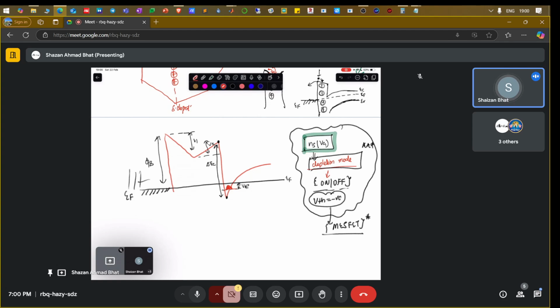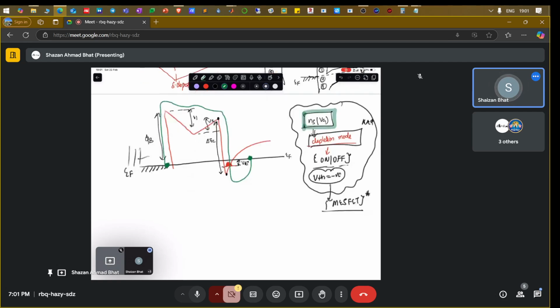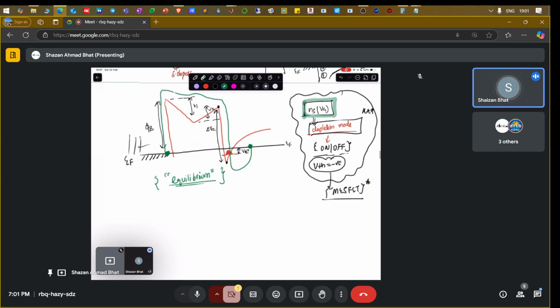So that's why we are going to compute it by computing the voltages, just like going through a loop, starting from the Fermi level, going towards the higher end, towards V1, towards V2, then coming down, then coming back to this Fermi level, so that the loop can be finished. It's just like summing all the voltages and equating them to zero, because this is all in equilibrium, remember. So there will be no net flow of charge. This is just in equilibrium.